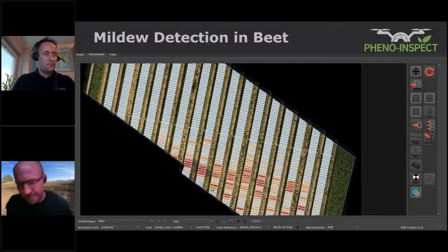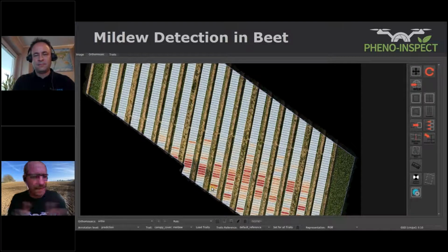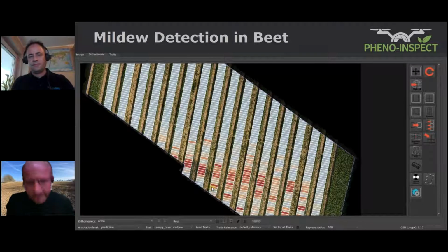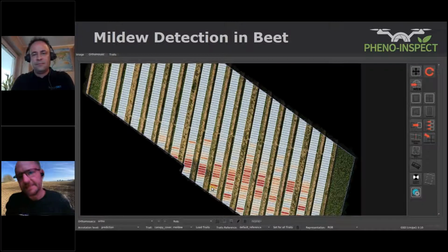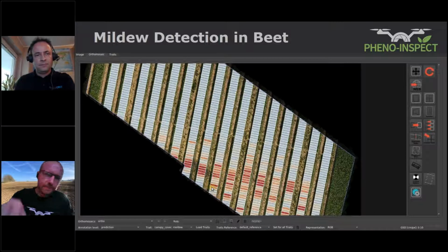And here's another big benefit, because the drone pilots who are listening now will know about it. There is always a recommended time when you should fly. Best around noon, plus minus 2 hours, and so on. Then you get the best images, the fewest effects, and so on. I say if you use high quality imaging sensors and our technology, you can basically fly from morning to evening, because this is really a data set which was captured under the worst conditions.